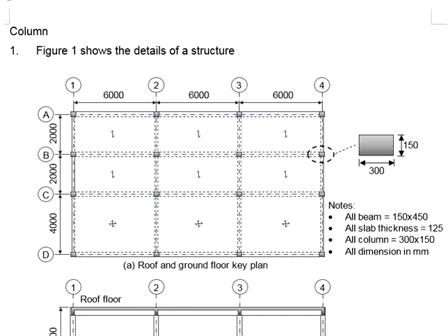This gives you an idea to decide the orientations of the column. For economical solutions, if you anticipate the moments will be larger in certain directions, it is always good practice to have that direction be the major axis. This can save you a lot of reinforcement.